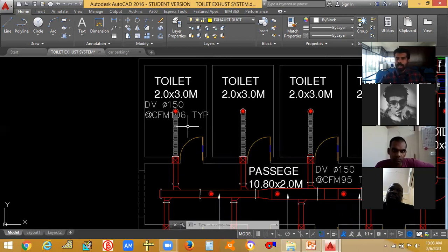You have to give two values in the duct sizer software. One is the CFM, that is a must. The next thing is you can give velocity, or static pressure, or friction loss. Better you give the friction loss as 0.1 in that friction loss column in the duct sizer software. So you will be getting the duct size.